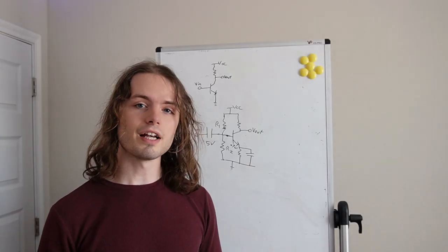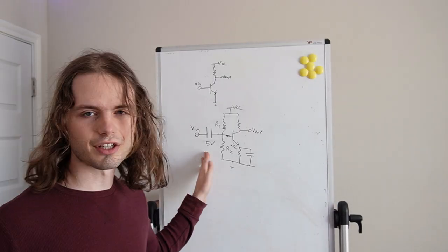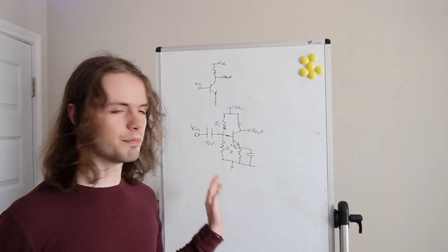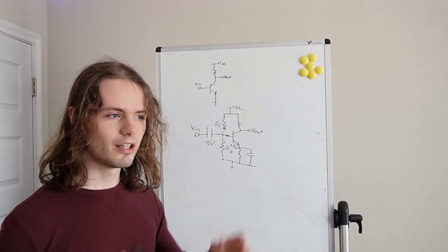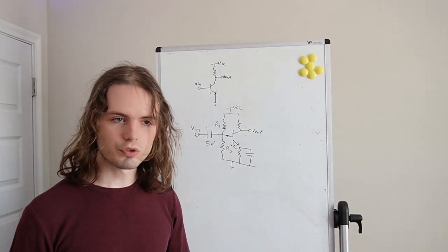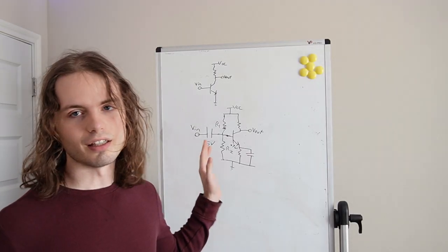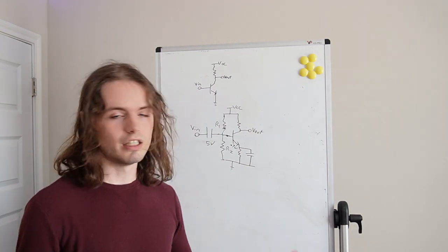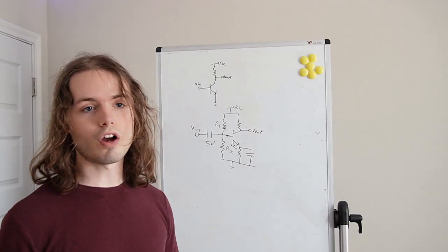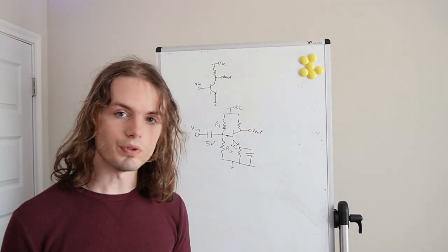At this point, you may be asking yourself, didn't we invent this problem? If we just didn't have this capacitor here, then the bias wouldn't be an issue because we know that the input can ride some DC offset. Yes, that is technically true, but you don't know what your input voltage is going to be offset by. If you can choose to offset it by 0.7, you could maybe choose to do this, but oftentimes your signal will not be precisely at the bias point you need it to be.